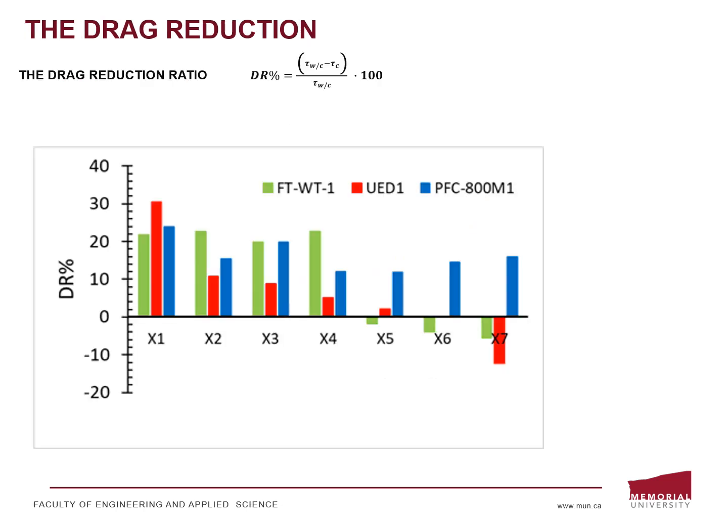This performance can be evaluated by the drag reduction ratio calculated from this equation. From this comparison, we can see that the FBC has a stable drag reduction with an average ratio of 18%, while Ultra Dry and FTMW showed drag enhancement in the second half of the surface, but they produced average drag reduction of 8 and 11% respectively.